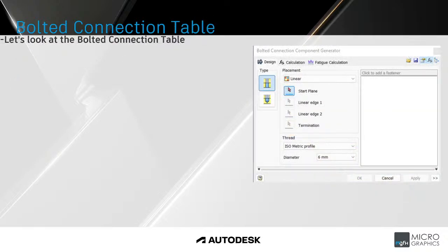When you select the bolted connection, the table on the right will appear. Like you can see here, you've got a few options you can choose from. So let's look at the difference. First we've got the type. You get two types, your through-all connection type and your blind connection type. A through-all connection type goes through all holes or is drilled through all the material. A blind connection type is where the last hole is blind.